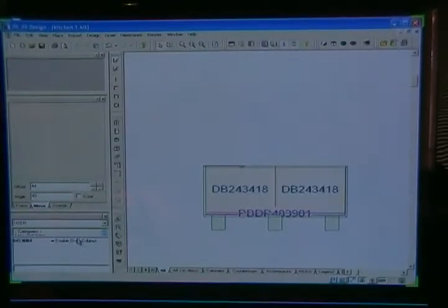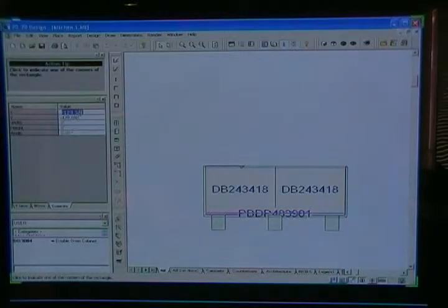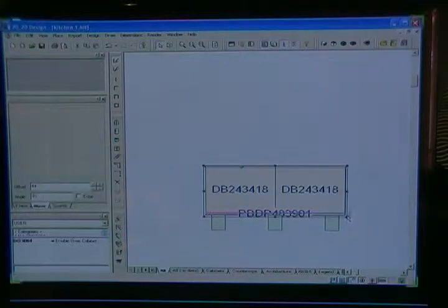Well, we can just simply drag and drop a countertop on top of this, or we can go into the 2D drawing section that we have in 2020 Design. We're going to go to draw, and in draw we have line, running line, and so on until we get to rectangle. We'll select rectangle, and I will select the corners that I need. Basically, I'll take this corner to this corner and create a rectangle around this whole island.